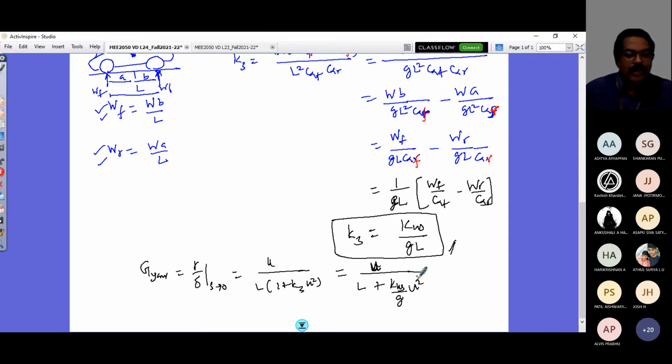So what is the unit of this? The unit of this is yaw velocity. It is sort of rotational. When you see from top, the change in orientation of your vehicle is what is witnessed by yaw velocity. So it would be given by radians per second, divided by steering angle, which is in radians. So the unit of the steady state gain, that is the yaw velocity gain, is radians per second per radian, right? That's what you should understand.